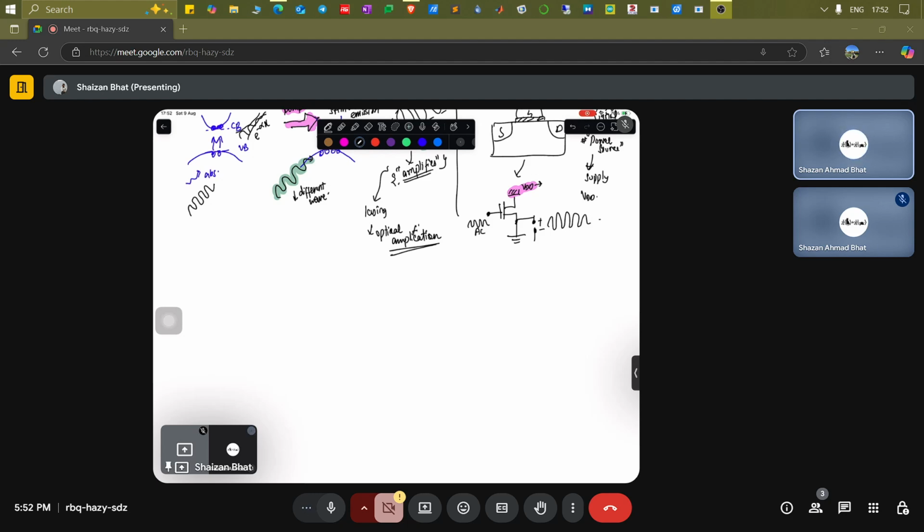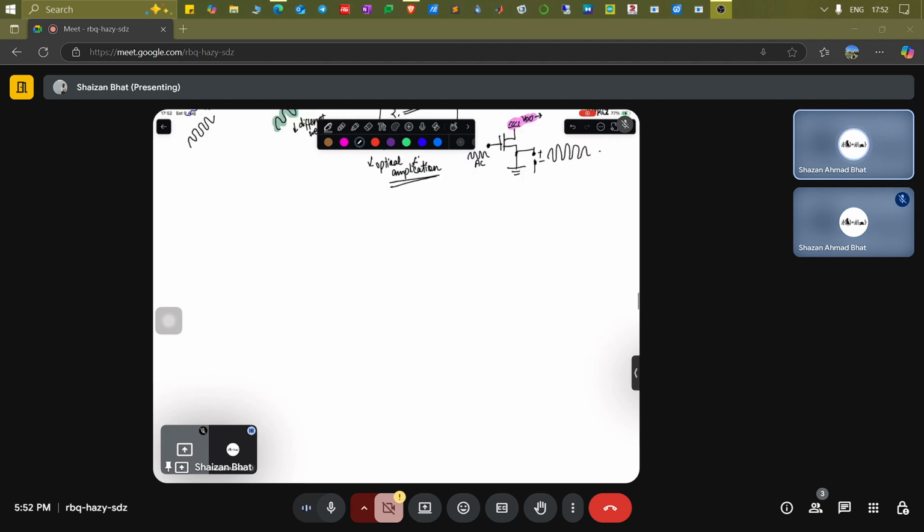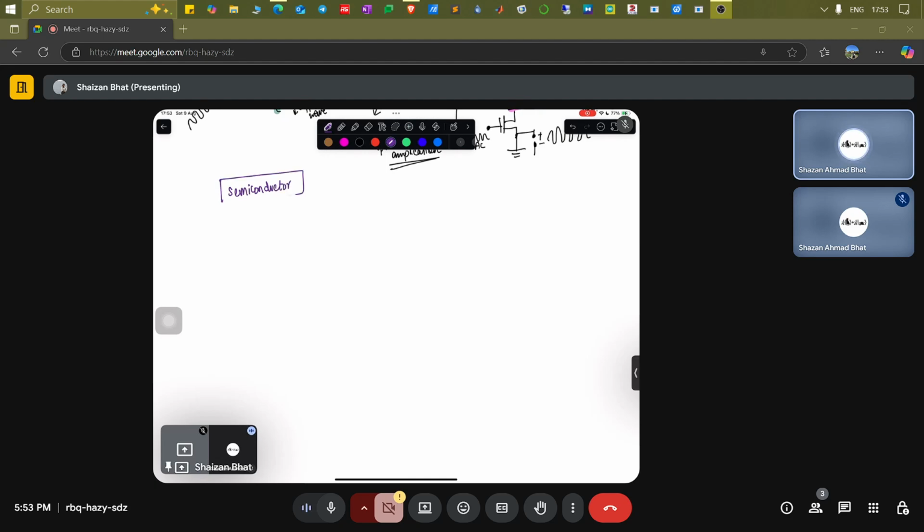That's about it. Now, what basically happens? There's a concept behind it. Why does this happen? Let's say, for example, we talk about semiconductors in general, under an equilibrium and a highly non-equilibrium scenario. In equilibrium, you know that the law of mass action holds. That means n times p is equivalent to ni squared. This is the law of mass action.